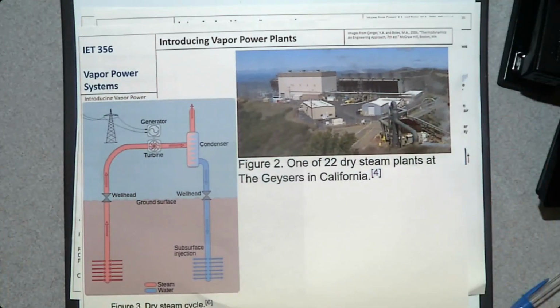Geothermal power plants. So we make a hole on the ground and pump water on the ground, and we know that down there is hot, right? Think about volcano. So when steam comes out, we use the steam to run turbine, do all the rest of the things to produce electricity. That is geothermal power plant. So we pump the hot water out of underground, run the turbine, and use the water from nearby to reject heat. That's how we produce electricity.